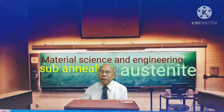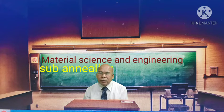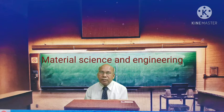Above the upper critical temperature, the metal contains austenite fully. Therefore, in sub-annealing, it's heated just below the lower critical temperature so that austenite is not formed. Then it's cooled slowly by switching off the furnace with the articles kept inside, and after cooling the materials are removed. Generally this process is carried out for low carbon steels.